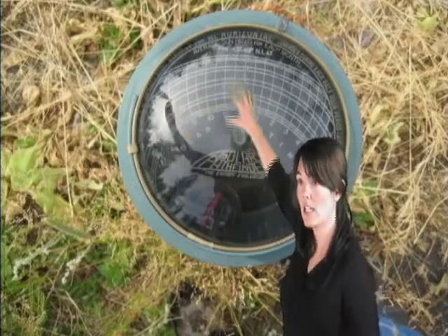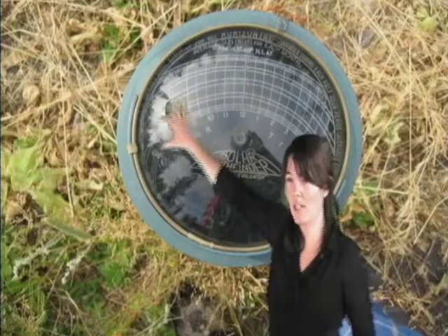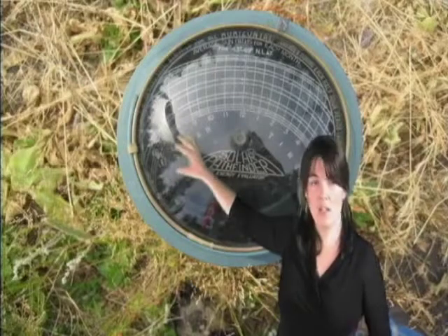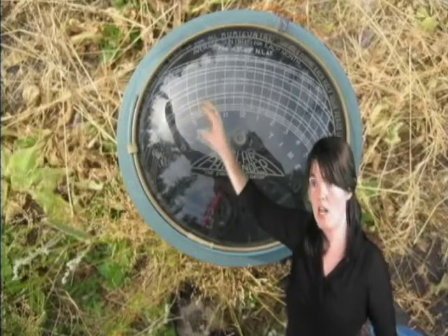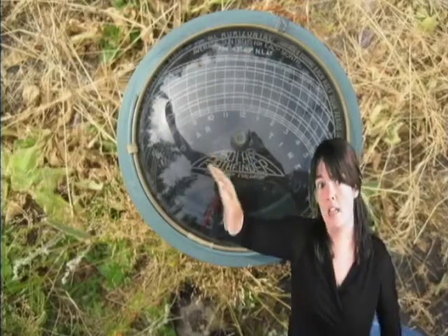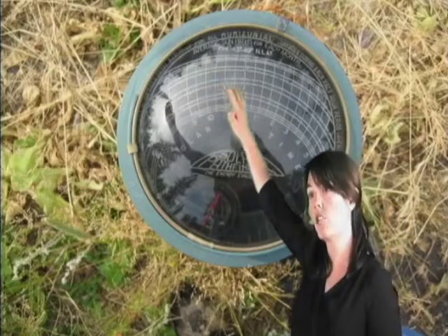So we can take a look at this and say, okay, if this is where my solar panel is, this tree might cause a little bit of a problem if we have the solar panels over here. There's going to be shading from our next door neighbor, so we don't want to put our solar panels there. And oh my goodness, this looks like a great spot because, as you can see, it's just sky. So this is a tool that we use when we go out to place solar panels or determine whether a site is going to be good for them, because solar panels are expensive. If you are in a spot where there's not good solar access, then you have to think if it makes sense to put solar panels on the roof of that house, or if there's another way you could do it in which they're elevated more, which would make them more efficient.